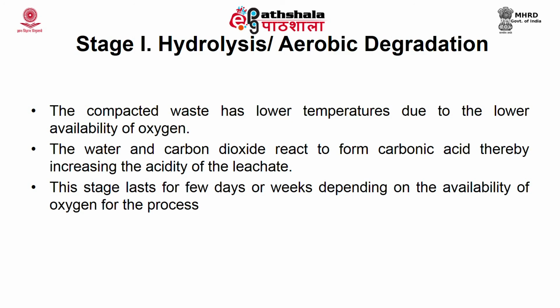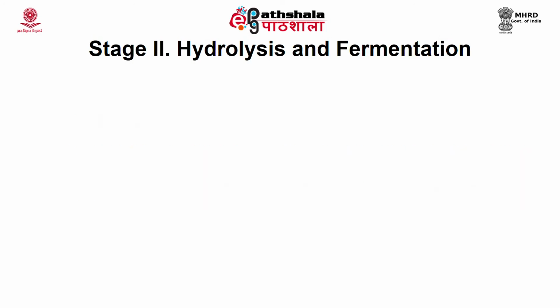The efficiency of the aerobic stage will always depend upon the amount of oxygen which is there, the void spaces, and it will also depend upon the degree of compaction and the air space which is locked in the void spaces of the waste. The next stage, that is stage 2, is hydrolysis and fermentation.